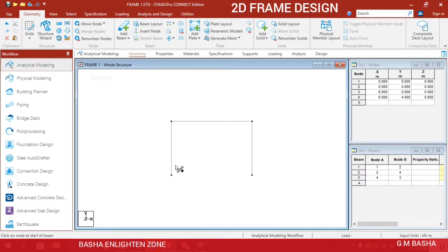So here, I will draw the frame based on the node to node connection, node to node joins through the add beam option. In the previous lecture, I added the beam based on the grid pattern, beam to beam connection. Okay, see here, this is another procedure. You can remember all the basic points. Okay, then what is our next step? I'll repeat each and everything. I will explain further in the next classes also, so just to go for the design.